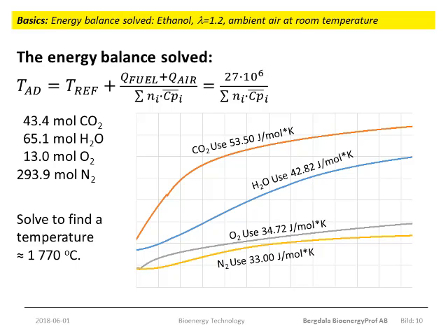Use the values in the slide to find that the maximum temperature in a well-insulated combustion chamber would be about 1750 to 1800 degrees C, which is more than 350 degrees higher than the required temperature for glass fining. So bioethanol could well be used as a fuel to produce container glass.